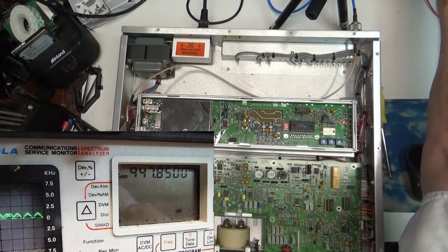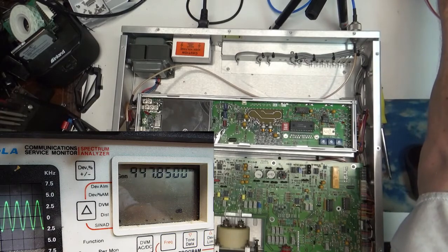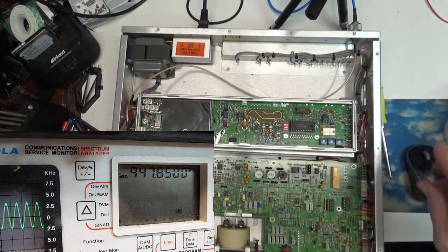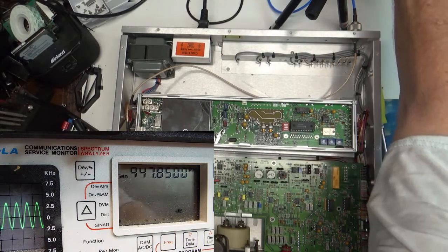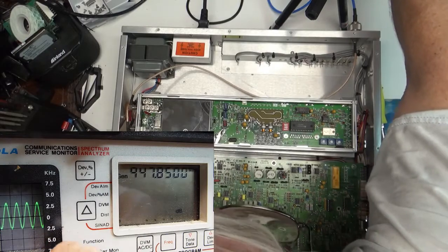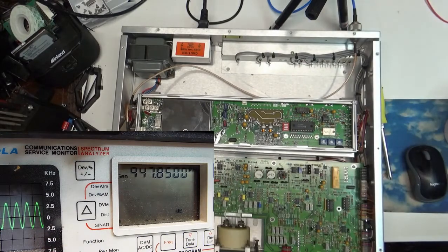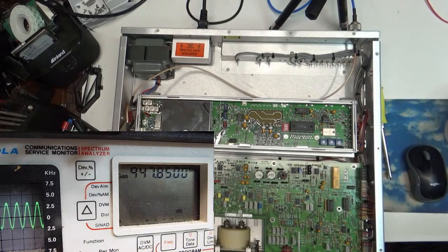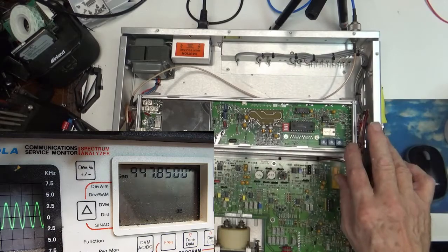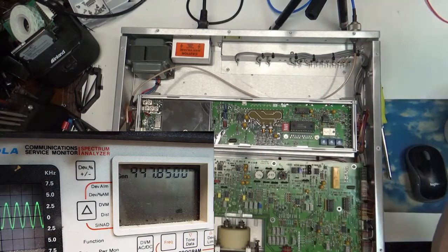We're going to give it some modulation, and we're going to give it enough signal to lock it in. Remember, you have to do your adjustment of your AFCs the same way on this one as on the other. You put it on AFC, you get it to the center.